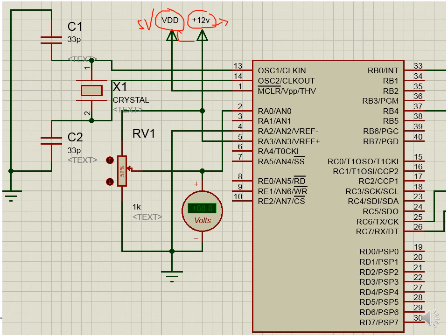Here for the power, I connect the plus to pin 3 and the minus to the ground. And I have to connect the ground of the 12 volt and the ground of the 5 volt together.